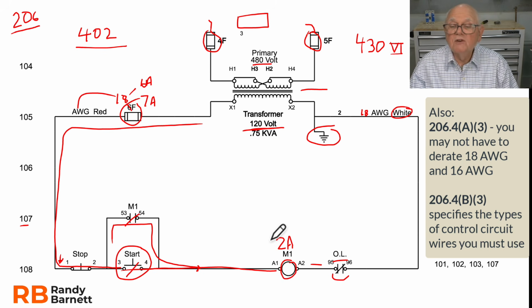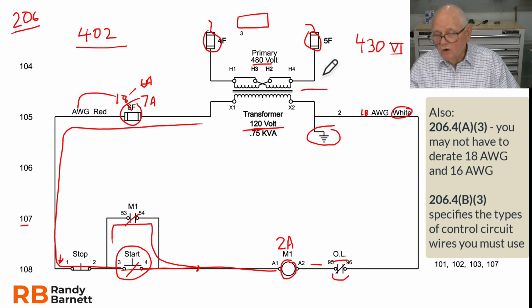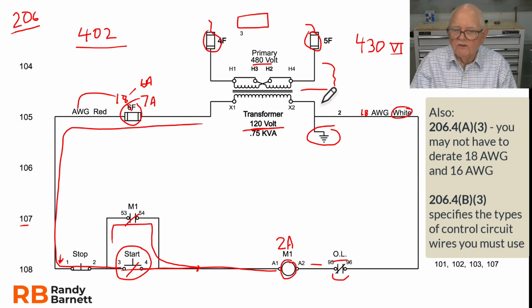And remember, I've also got to go look in Article 430, specifically Part 6 on motors, for information on my control power transformer up here and installation requirements for that. So you want to make sure and take a look at 430. Then you could get into other equipment as well, couldn't you? Suppose this motor were actually an electric motor driving a fire pump. Oh, that's pretty important.